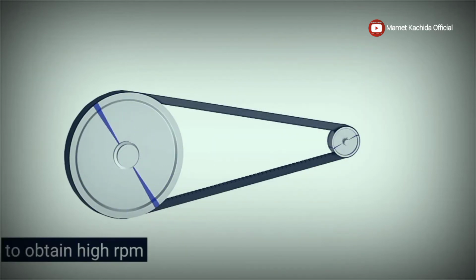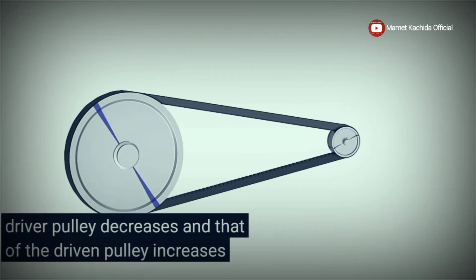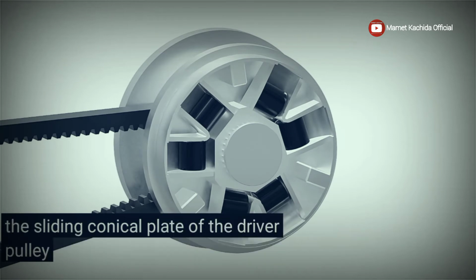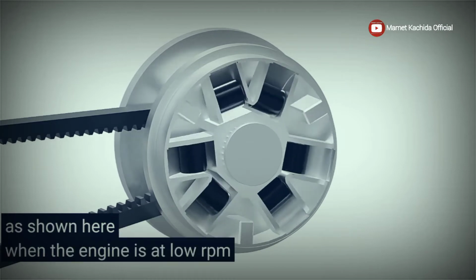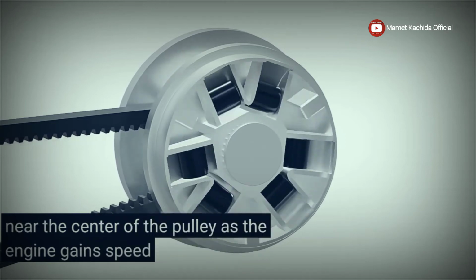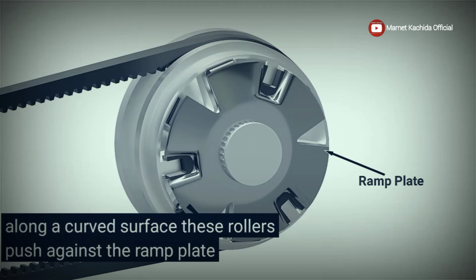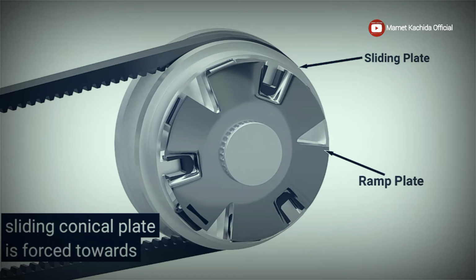To obtain high RPM, the diameter of the driver pulley decreases and that of the driven pulley increases. Let's understand how this is achieved in the actual scooter CVT. The sliding conical plate of the driver pulley has a set of rollers or sliders as shown here. When the engine is at low RPM, the rollers are held near the center of the pulley. As the engine gains speed, centrifugal force causes rollers to move outwards along a curved surface. These rollers push against the ramp plate. Since the ramp plate is fixed, the sliding conical plate is forced towards the other plate.